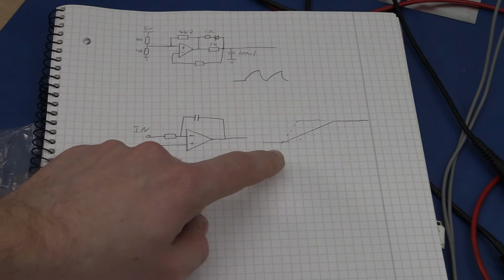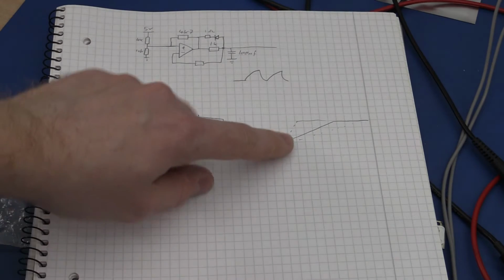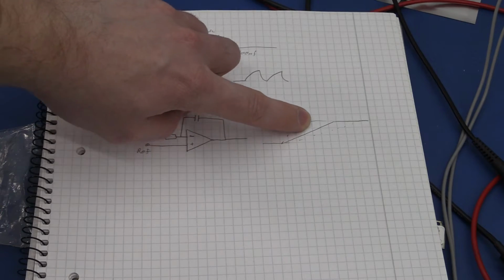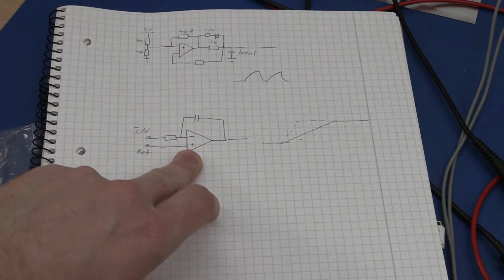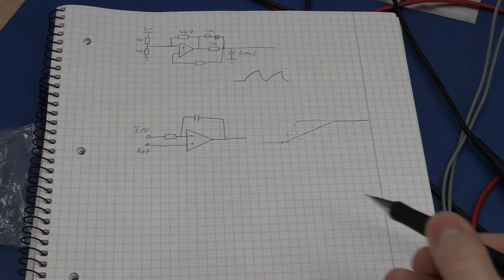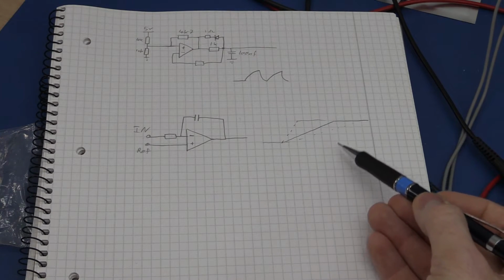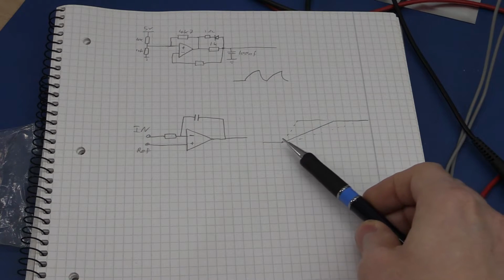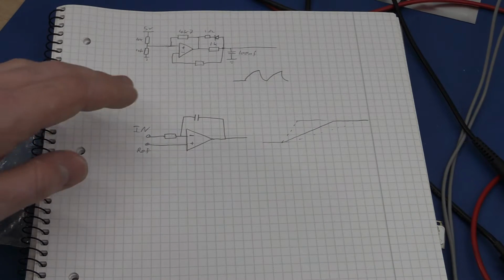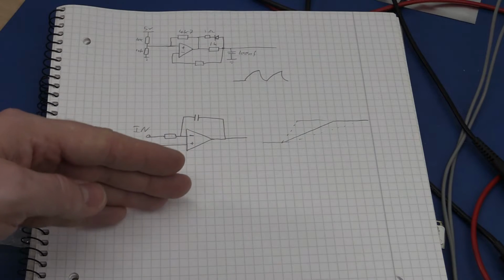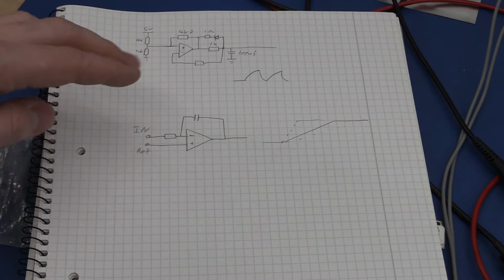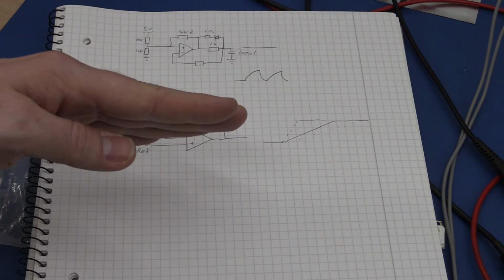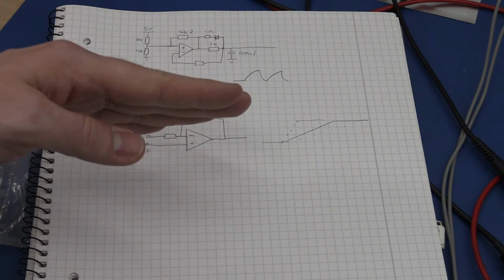So the idea is that in our final circuit you would not see a ramp as the output of the integrator. You should see a straight line somewhere in between the two rails. The reason we don't see a slope is because the regulation will make sure that the voltage drop that we measure is always a little bit higher, a little bit lower.